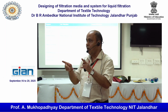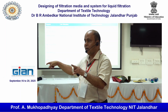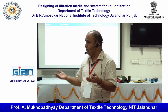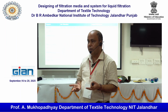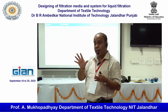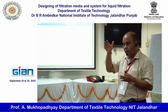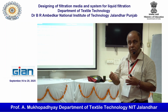Although there are people trying to compare this material having 40 micron with another material of 50 micron. So 50 micron will not be superior as compared to 40 micron. What is the relevance of comparing 40 micron and 50 micron? Because in both cases it is much higher than 2.5 micron, so that doesn't hold good. That is the point. So mainly the area matters, because of the lot of parameters which can have influence, the surface area matters. And the nature of the pores also matters for arresting the particle.